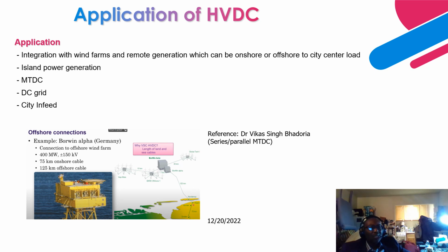to utilize high voltage DC transmission technology, especially the voltage source converters, that have the ability to synthesize their own voltage and produce power. And this phenomenon is called a black start. It has the ability to provide power when you don't have any reliable source of power.